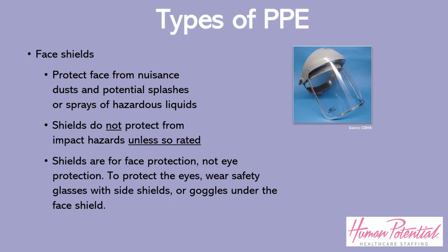Face shields are intended to protect the entire face or portions of it from impact hazards such as flying fragments, objects, large chips, and particles. When worn alone, face shields do not protect employees from impact hazards. Use face shields in combination with safety spectacles or goggles, even in the absence of dust or potential splashes, for additional protection beyond that offered by the spectacles or goggles alone.